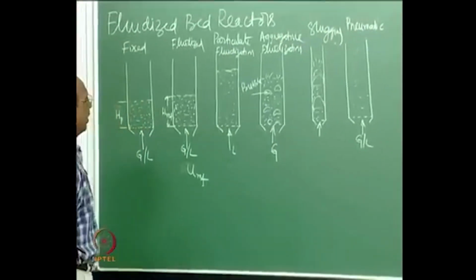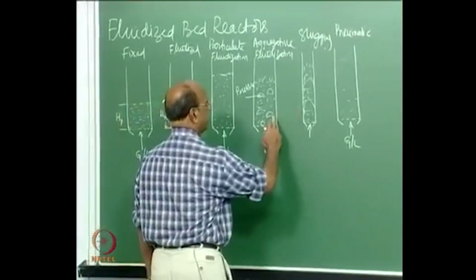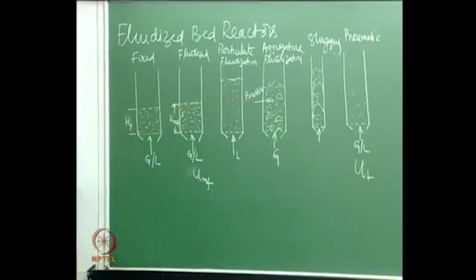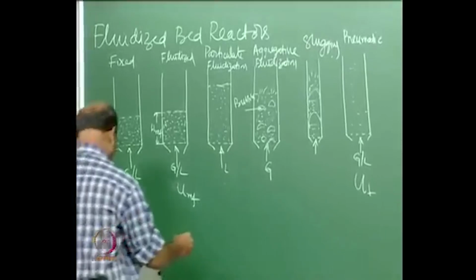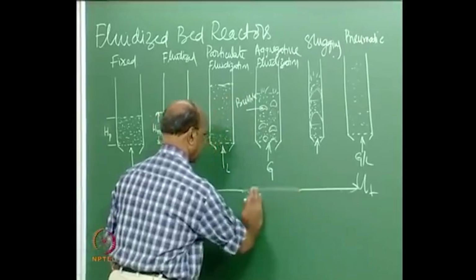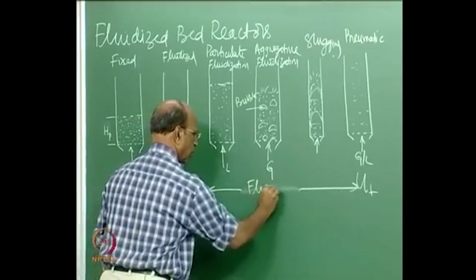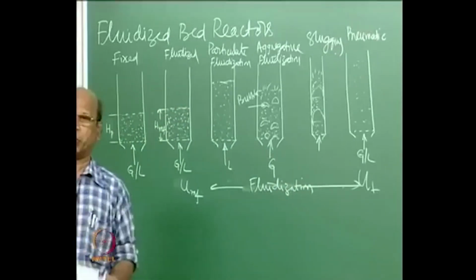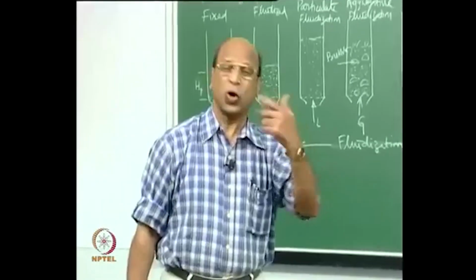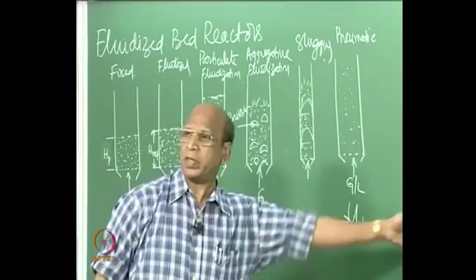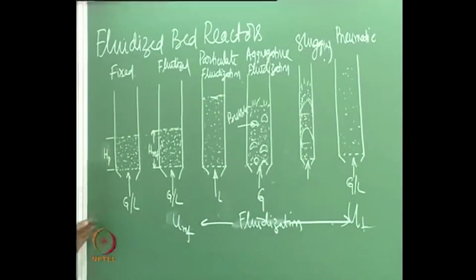Okay, good. Yeah. So, this is pneumatic conveying, and now the fluidization, yeah, beyond somewhere here you have it. If I take that as ut, terminal velocity, your fluidization range is from here to here. That is why, as I have been telling you all the time, you have the flow regimes. Even here we have a flow regime. Beyond this, no one can operate that as a fluidized bed, and beyond this also no one can operate till here.